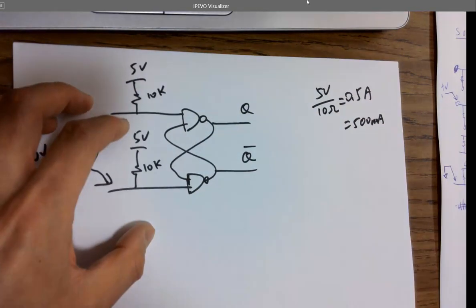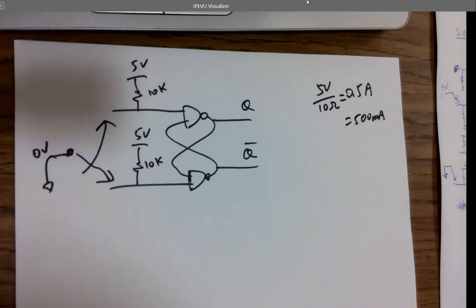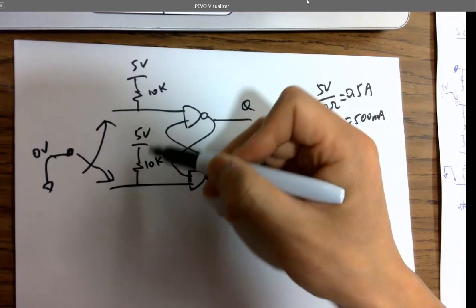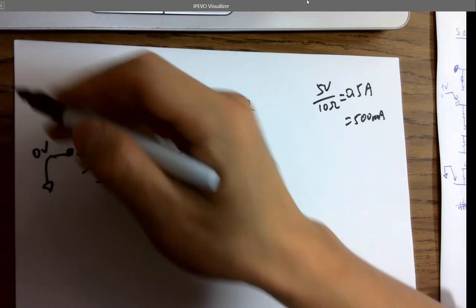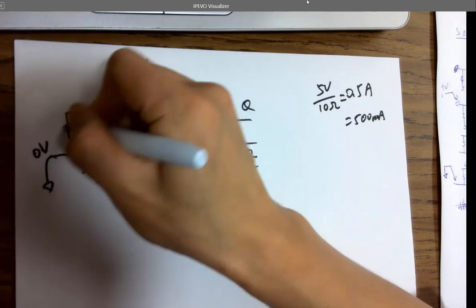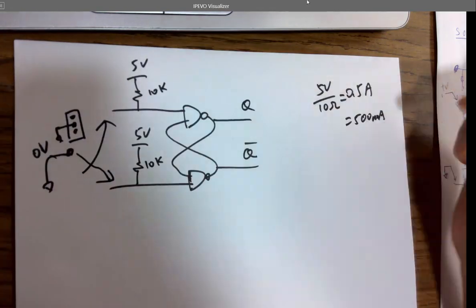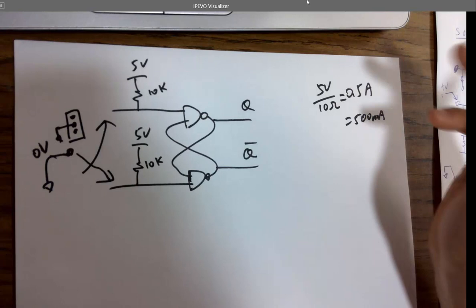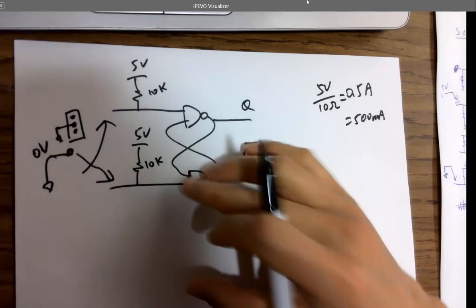But compared to the NOR gate, where you give 0, 0 as memory, that's the only difference. So if you only have NAND gates available in the lab, you want to use a pull up resistor to 5 volts and short the switch to ground. You have 3 pins on the switch, and the middle pin should be grounded, right? Make sense? Super practical circuit.